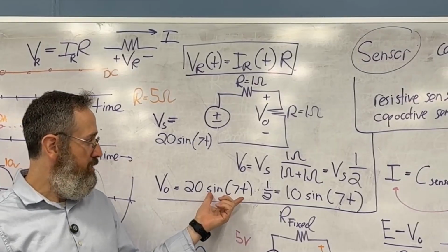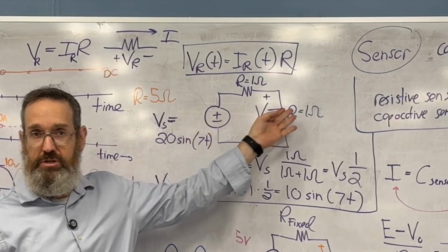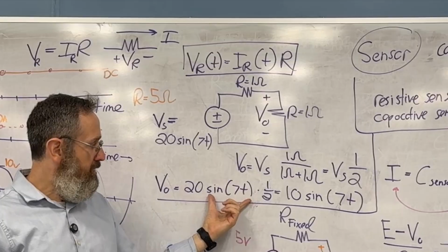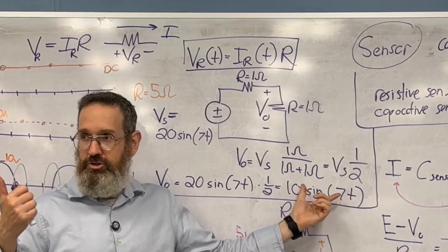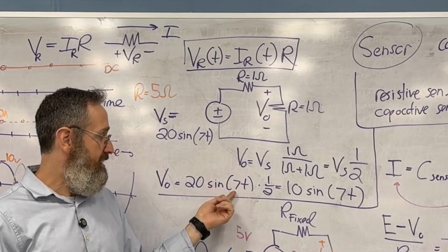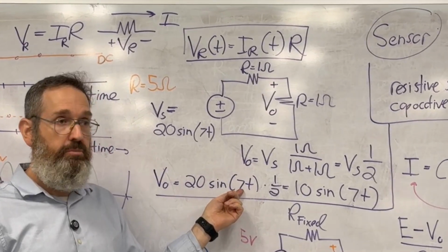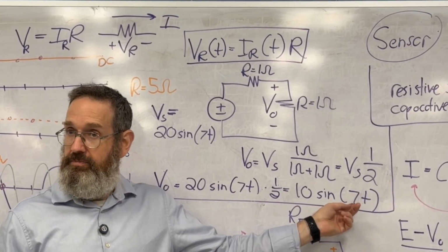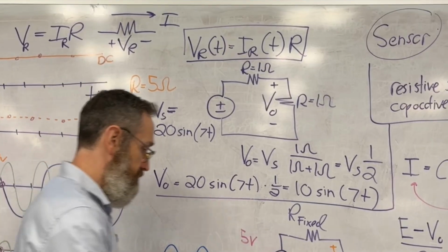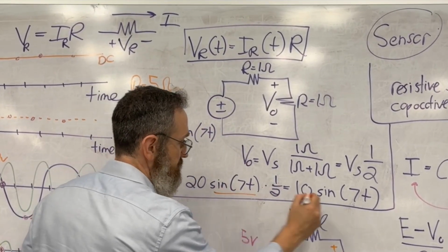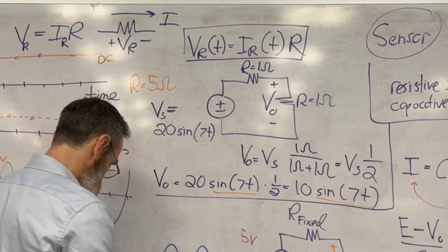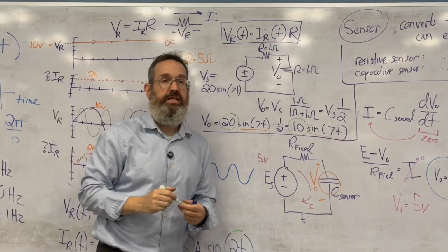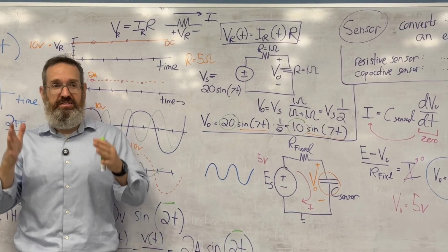The input was a sinusoid, right? In this case, the input is a voltage and the output is a voltage, no problem. So the input was a sinusoid. Was the output a sinusoid? Check. The input had this frequency, which is governed by the number before the t here. Does the output have the same frequency? Check. Did the size change? So these were sort of our fixeds. Did the size change? Yeah, the size changed, because that's allowed by sinusoidal steady state analysis.